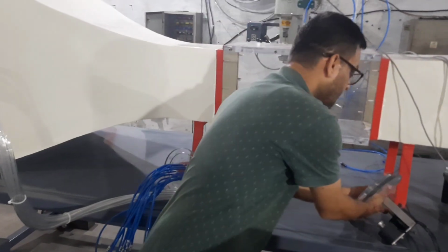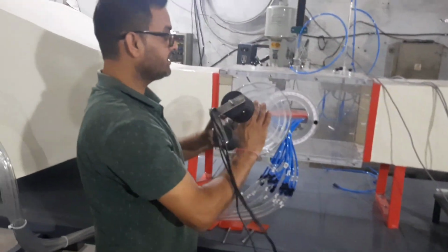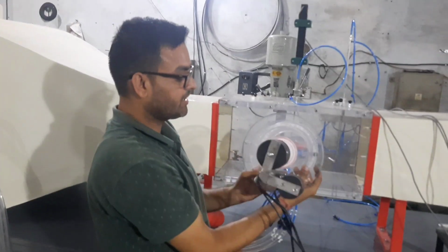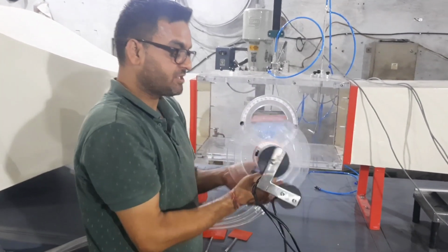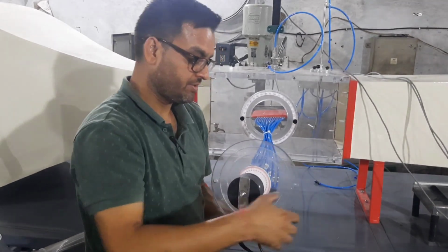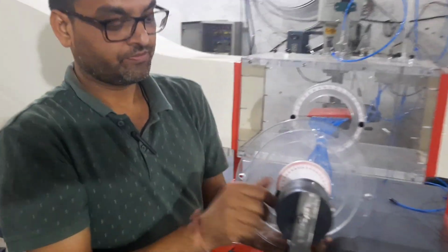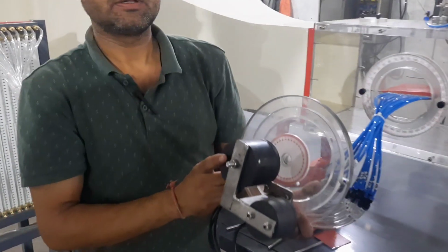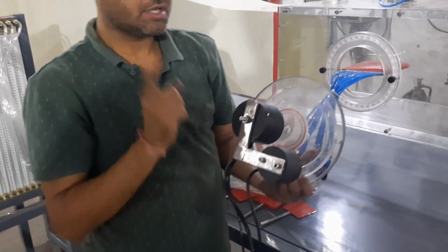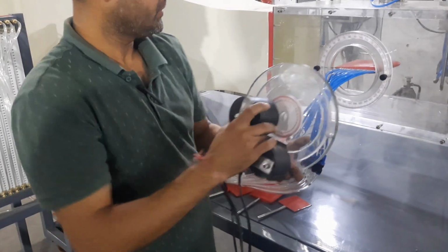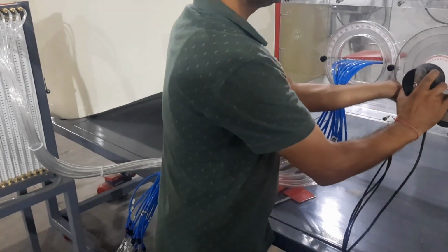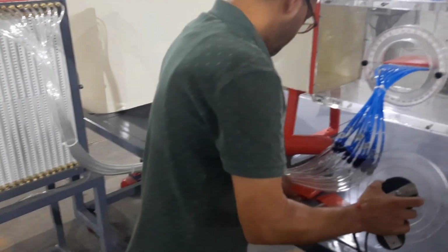Apart from that, another accessory can be easily fitted in a similar manner, as shown earlier, with the help of the two knobs, and this is a displacement unit with angular feedback and a 3-axis load cell. This means you can find out the drag force, lift force and the pitching. This can be easily fitted like this, and you can fit your model under study here.